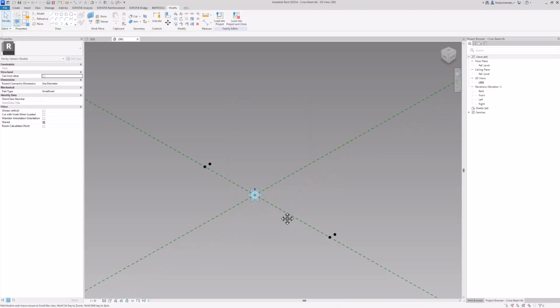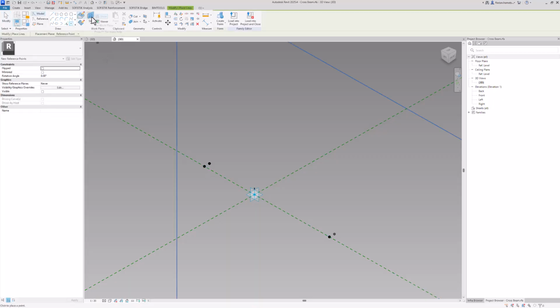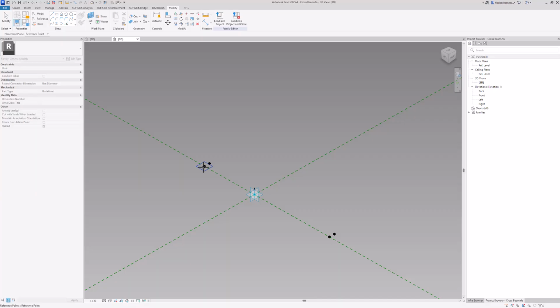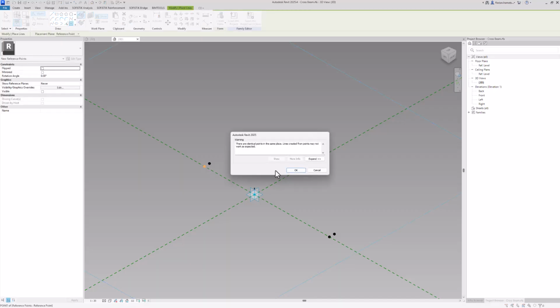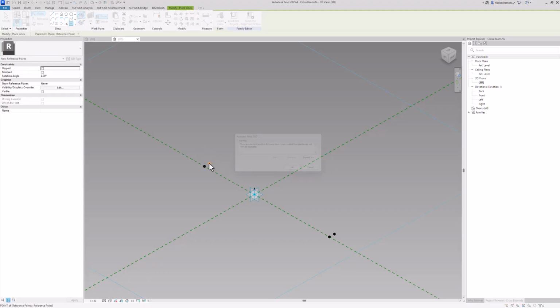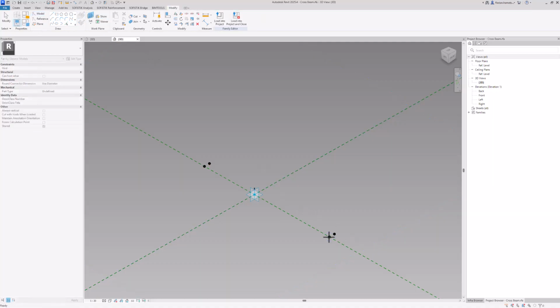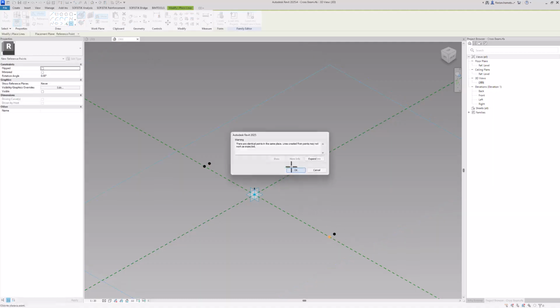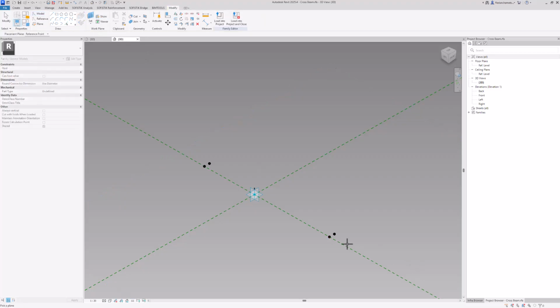And now basically to get a rectangular section, I select point reference once more and select the proper work plane of my first point. I click on set, select the horizontal work plane of the second point, and I repeat this procedure for all my sides.